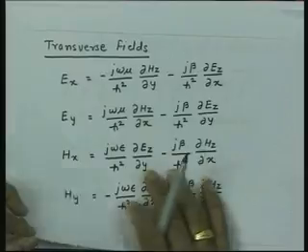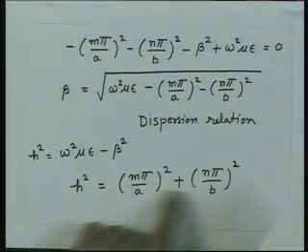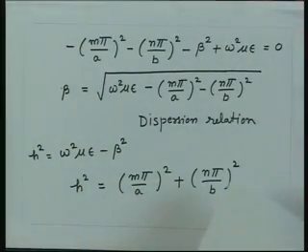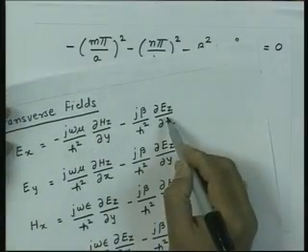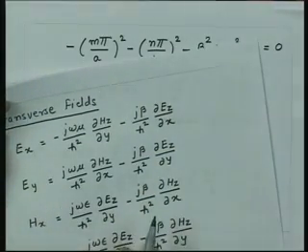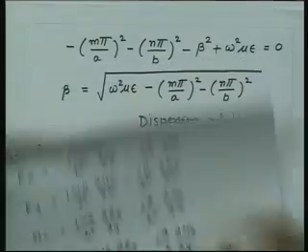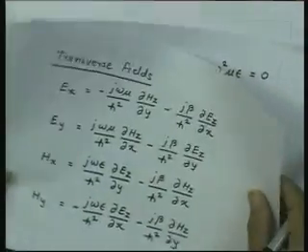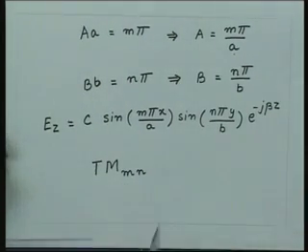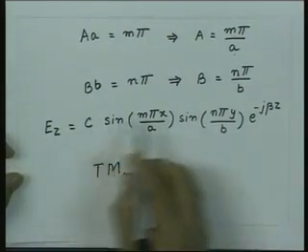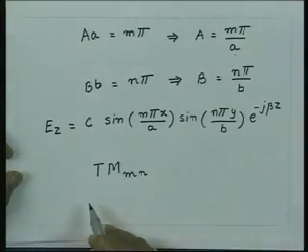However, now we are seeing that h is not equal to 0 when either m or n is not equal to 0, and then if Hz and Ez both go to 0, all transverse fields would go to 0 and the mode would not exist. So, for the transverse magnetic case, when either m or n is 0, this field will be 0, and since h is not 0, again the transverse field will go to 0 and the modes will not exist.